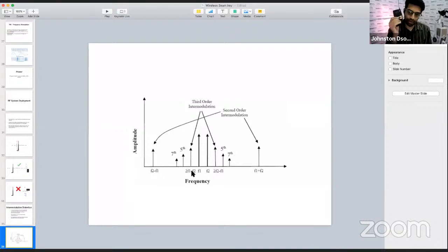Pretty much every brand has some way of scanning, and any professional system will always have a broadband scan. This system probably won't, because the BLX is an entry level system. It is tuned to certain frequencies and can only work on those; anything more or less than that, it can't. Whereas this is a professional system for cameras. It can scan the frequencies and tell you which frequencies are free and which are not.